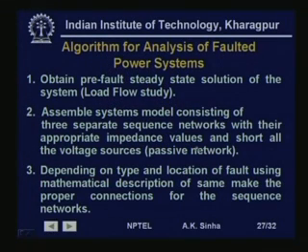So, appropriate impedance value and short all the voltage sources, that is, we have seen earlier that for computing the fault currents using the Thevenin's theorem principle, what we are trying to do is find out the changes caused by introducing this fault.